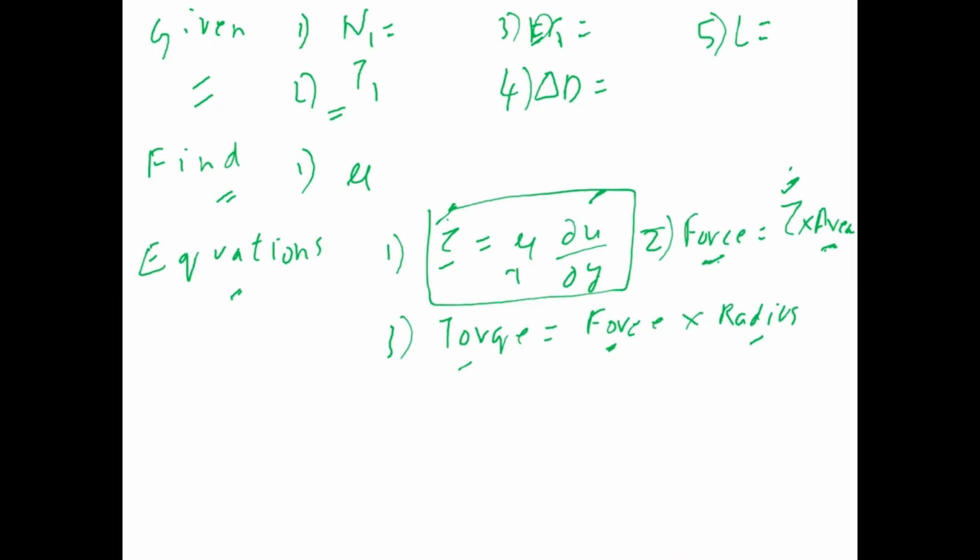For people who don't know this, I'll break it down step by step. If you want to find angular velocity, you can do so by multiplying RPM by 2 pi, and this is literally describing what I said. A revolution is 360 degrees, so 2 pi is 360, and how many revolutions I'm making is n1.